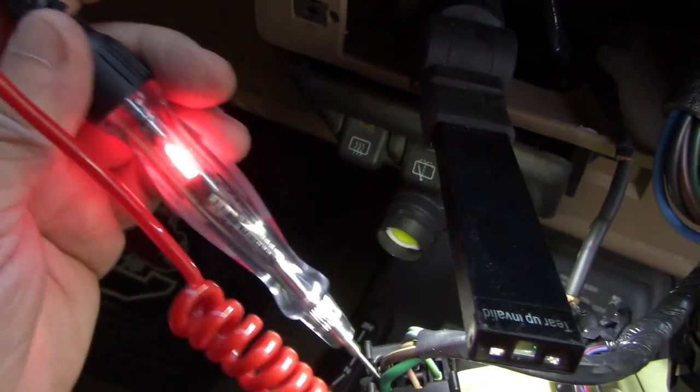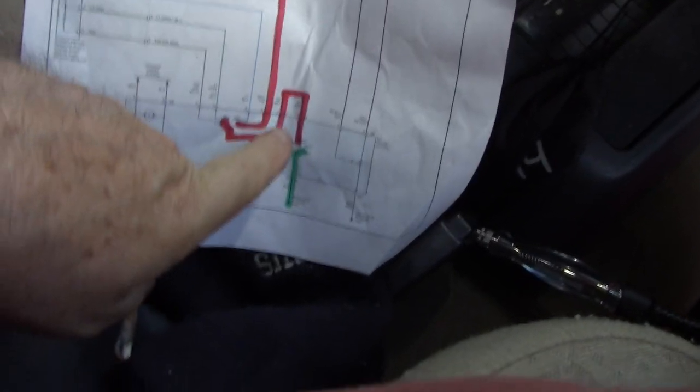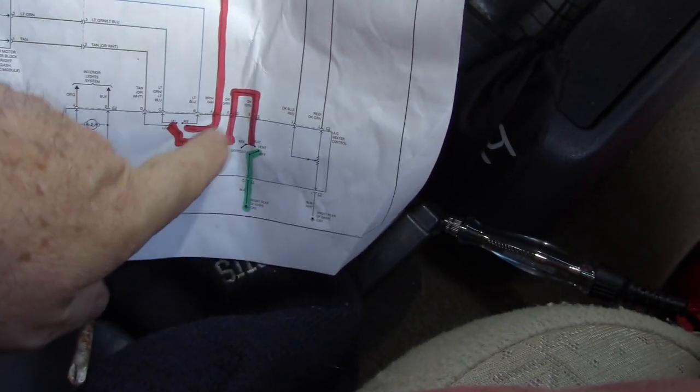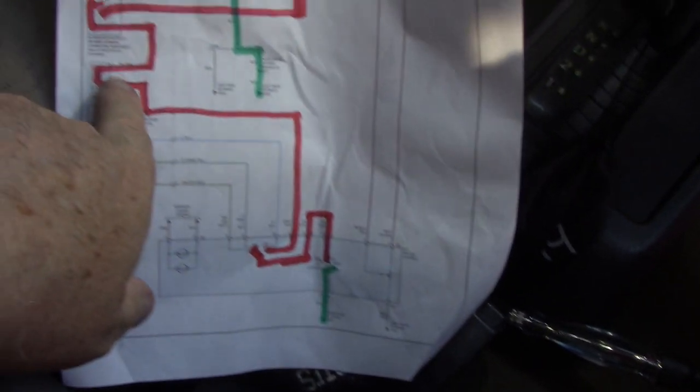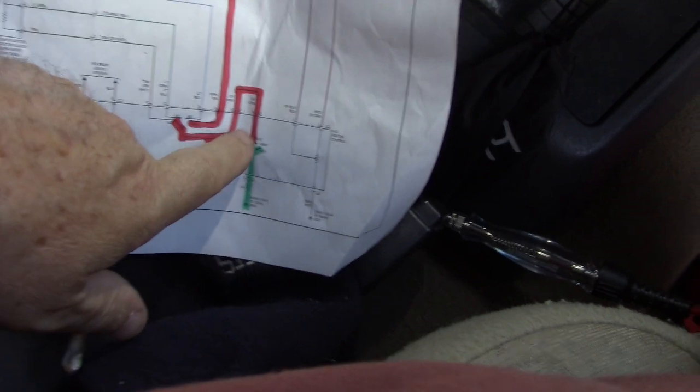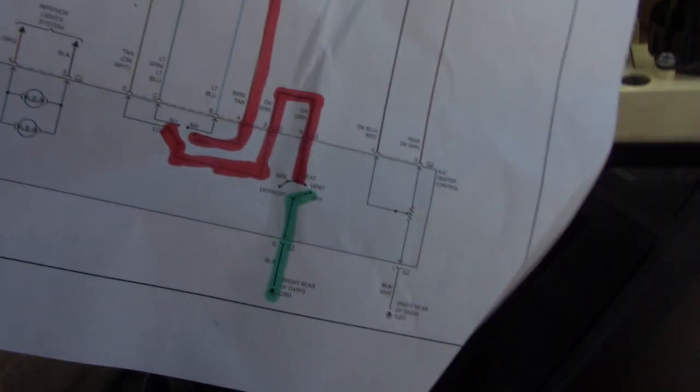All right, so just so we can verify everything we're doing, we have power coming out of the switch here all the way through. So that tells us our motor is good. We have power all the way through, and we're right here. So where does it go next? I think it's the same dark green that goes over to this selector switch, kind of like the mode it's in.